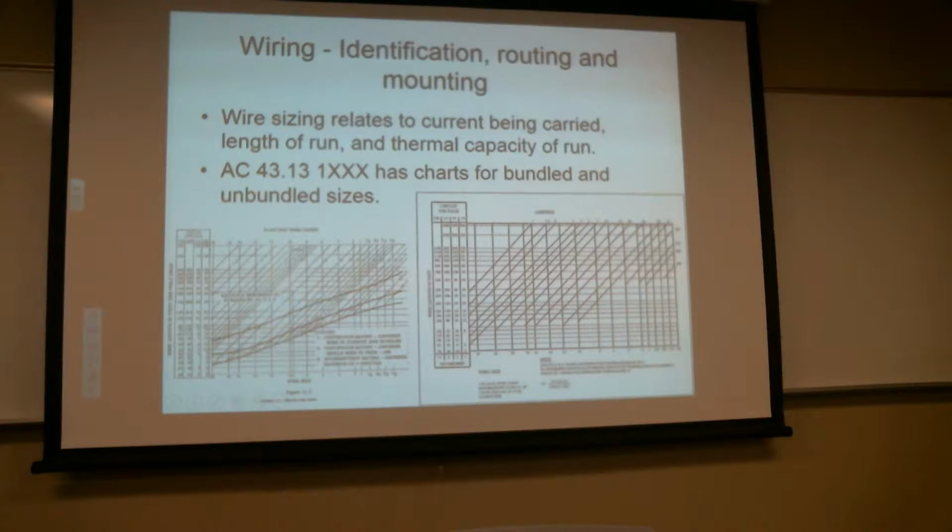Now, a couple of caveats that make our life a lot easier. One of them is the ATA, or Air Transport Association, along with several others, have created some reasonable standards for wiring diagrams and wiring labeling, as well as the mil-spec that tends to get used. Not universal, but those do tend to get used.